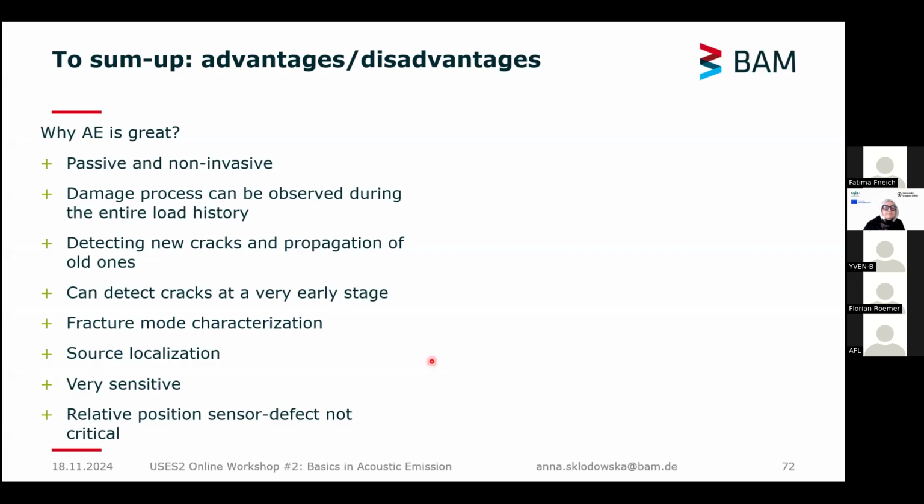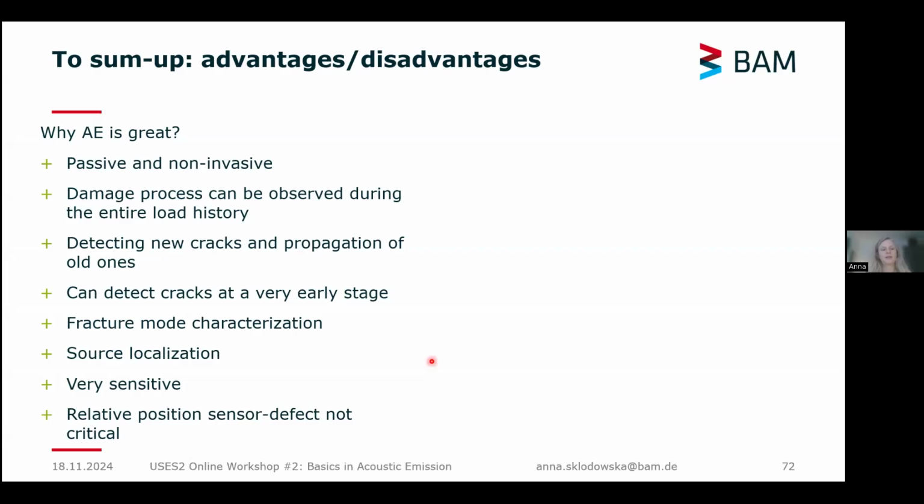It's a passive and non-invasive technique, and we can observe the damage during the entire load history and monitor this process during this time. It's great for detecting new cracks and propagation of old ones, and can also detect cracks at the very early stage of nucleation.